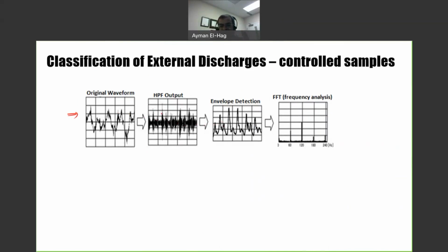So you see, this is the envelope of this one, and it will demodulate it over the carrier frequency of this country. So here our frequency is 60 hertz. In some countries it is 50 hertz. And then you will get here the f of t, and this is a typical f of t in North America. So this is, you see here, 60 hertz, 120, and 180.